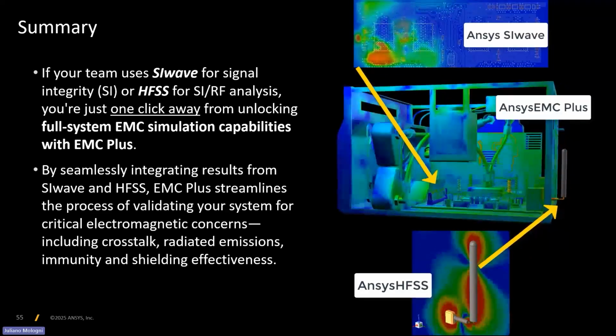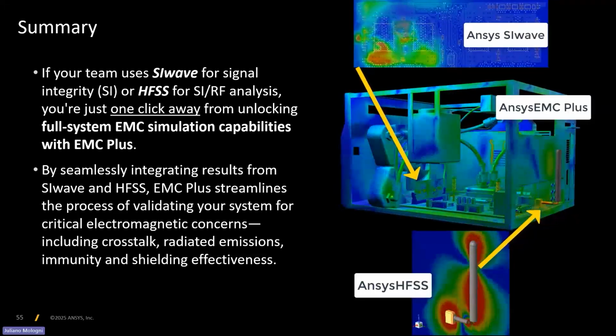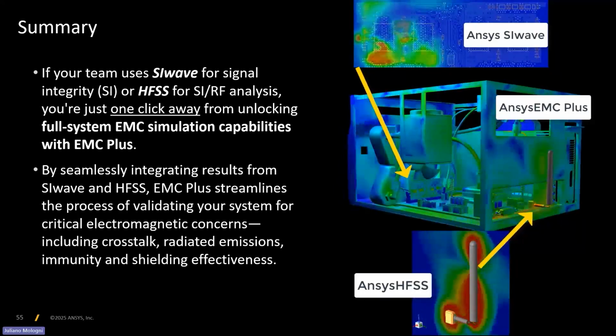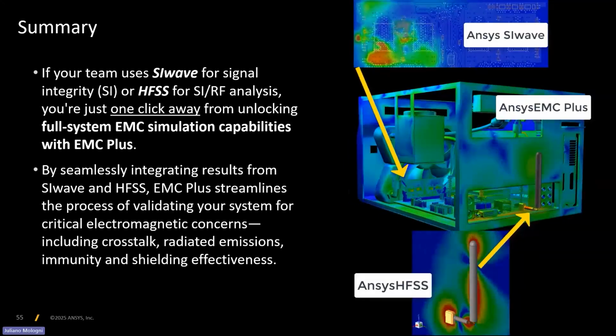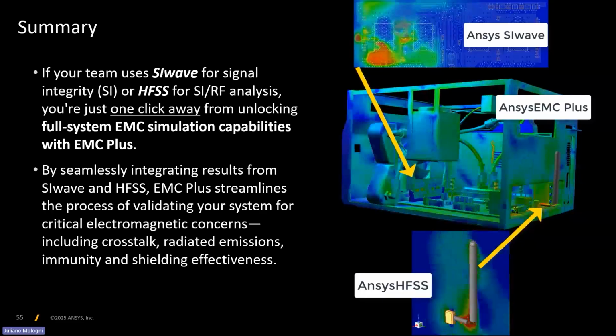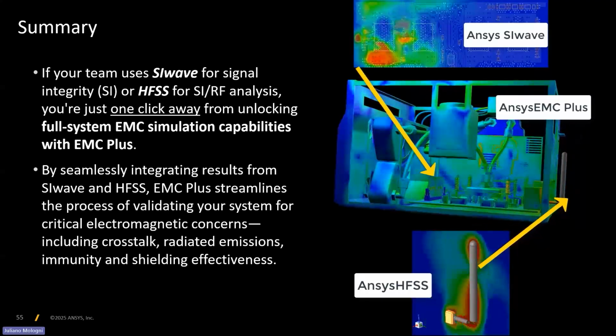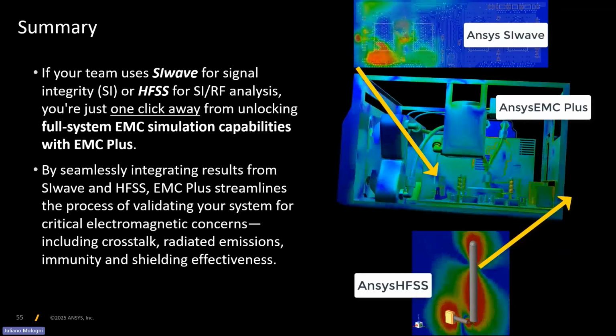It's an FDTD where you can have regions with smaller mesh, usually if you want to simulate a PCB in 3D or closer to models where you have small details, you can create a subdomain with smaller mesh cells. But you're correct; it's FDTD based on a grid.